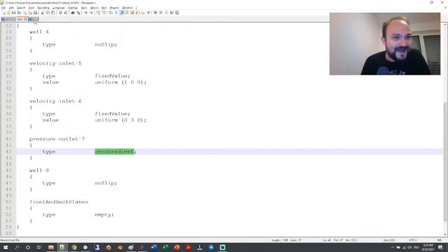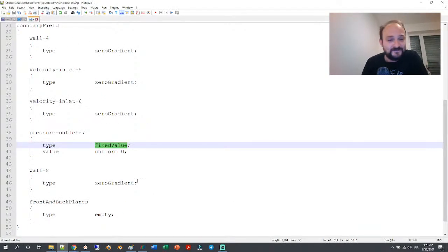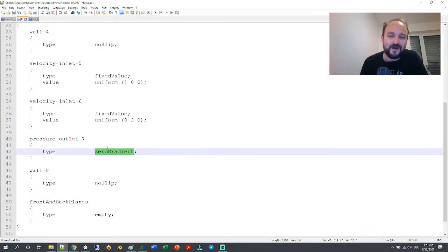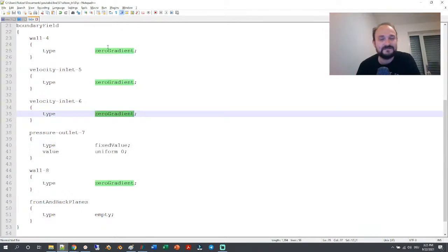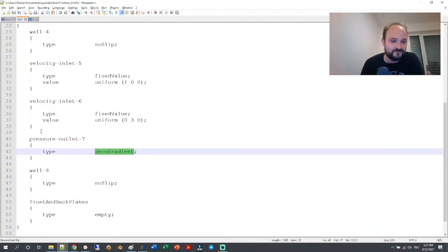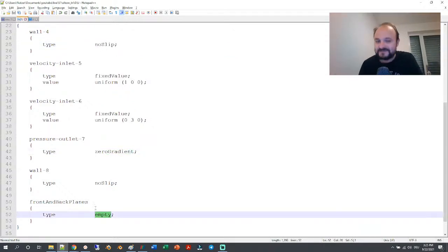And now I mentioned the pressure outlet velocity here as a fancier boundary condition. Of course, it's the outlet boundary condition. You can use inlet outlet, pressure inlet outlet velocity. Here it is, what's the pressure? Fixed flux pressure is the fancier boundary condition that you would use for the pressure. So sorry that I talk too fast. Okay, and then there is this empty boundary.